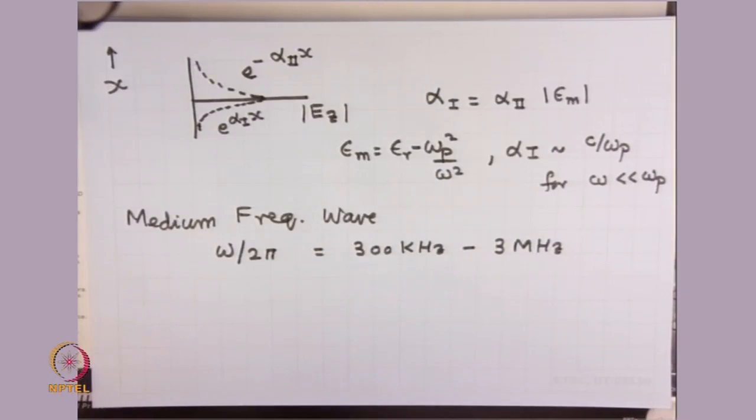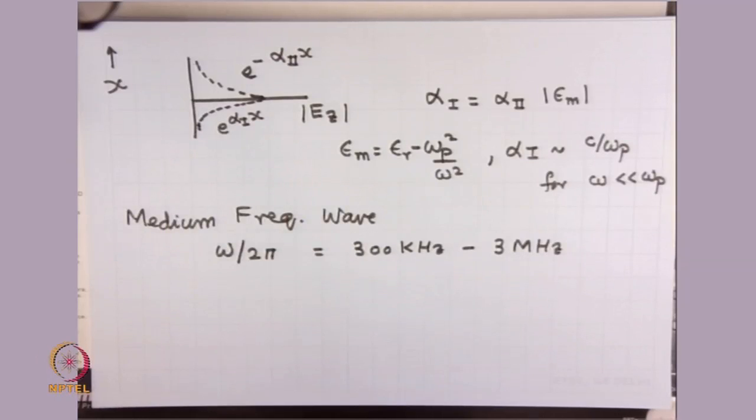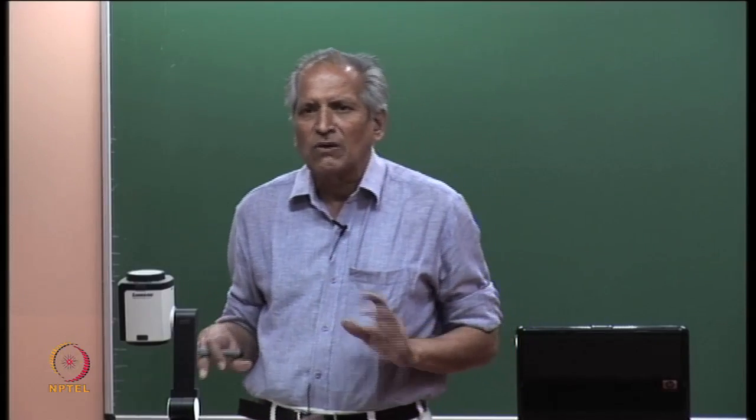So though the soil has soil particles separated from each other, or soil grains separated from each other by a certain distance or maybe connected to each other, the wavelength of this wave is very large, and consequently one can treat this to be a continuous medium. So there may be pebbles, there may be clay, there may be water molecules, etc. But you can average out the properties of the earth.